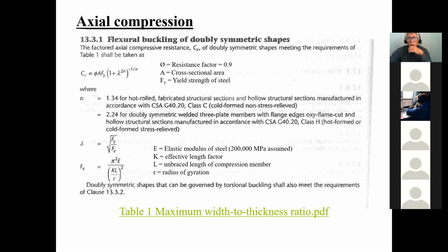The difference is that in wood, you have nice rectangular sections, you see? And the material is fairly weak. I'm talking about the resistance of the material. In other words, steel, you have 350 MPa. In wood, you have 9 MPa. You understand? To give you an appreciation.